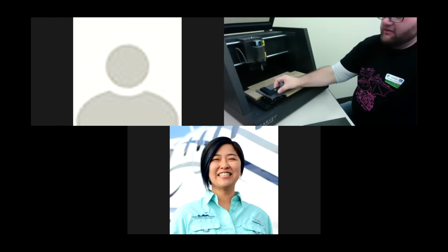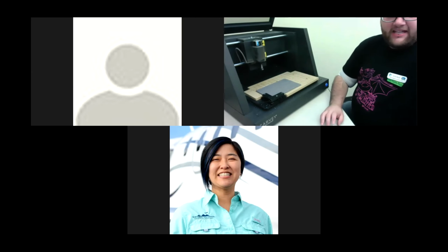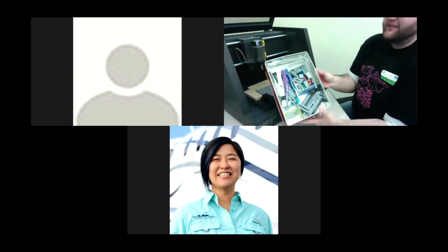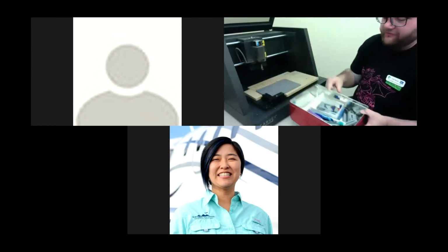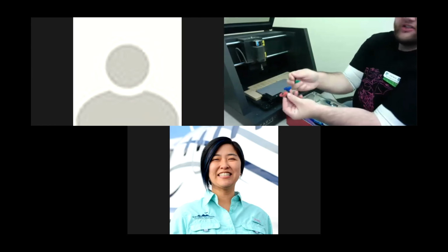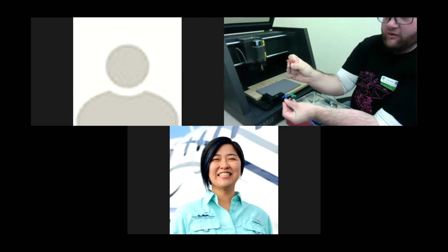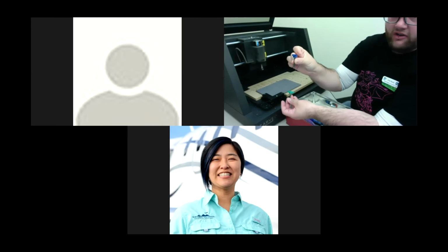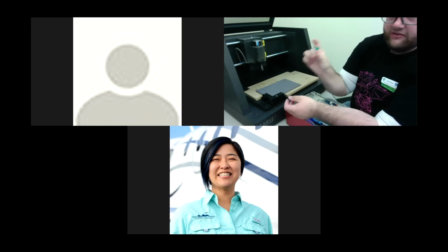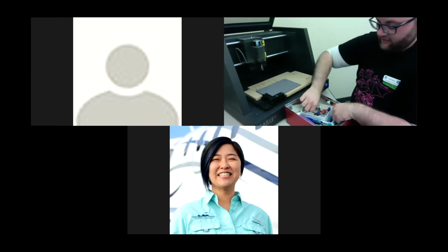Here's the smart clamp. So this goes and it clamps down the edge of the material. So what we do before we put the drill bits in is we have this really nifty box here with all these different clamps and all these different screws to hold the material down. There's actually 3 colors of screws. The red ones are for very tall material, so anything over 3/4 inch. The blue ones are for medium material, so anything 1/2 inch or over. And then the green ones are for thin material. So there are 5 screws per color, and we've got them in this box here.